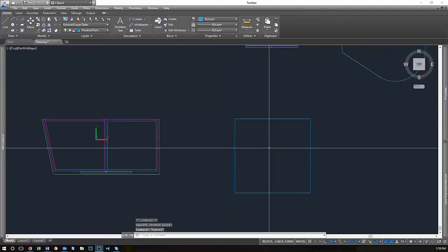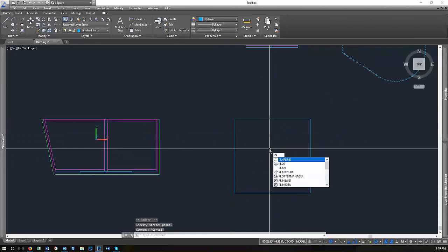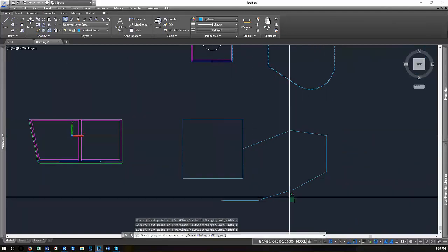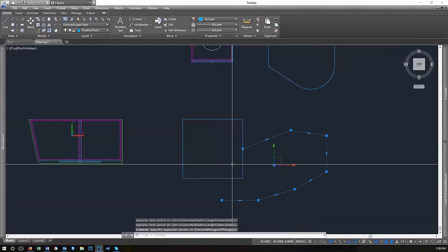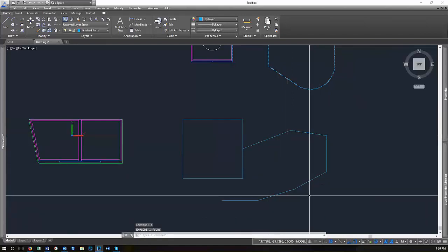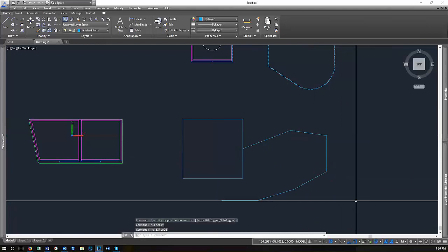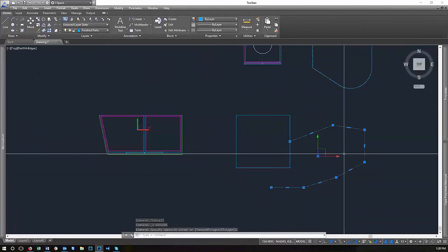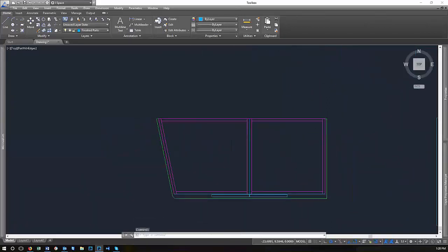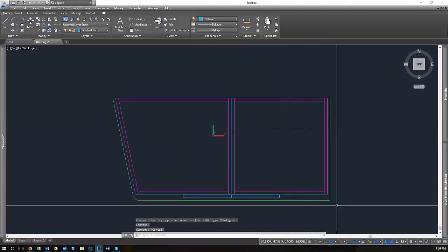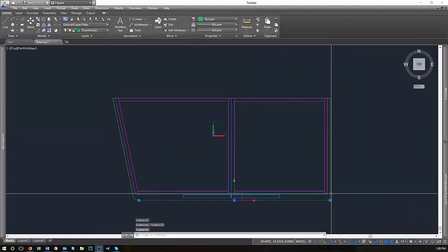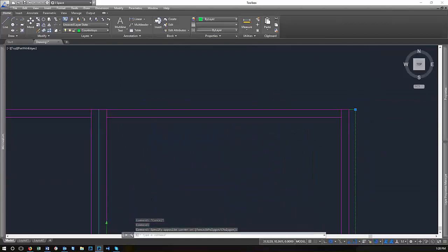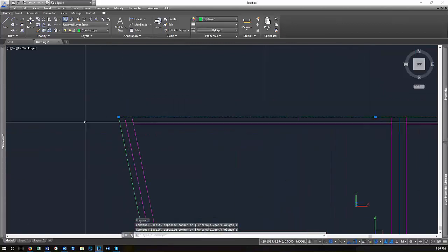And you can create one freehand by hitting PL. So that's a polyline. And you can click, and then wherever you click around the screen, it's going to make one contiguous line. And then once again, you can use the explode command to turn those into separate lines. But if you wanted one continuous line that you could select all at the same time, then you could have a polyline. Typically, I'll have my countertops be a polyline, and that allows me to select the entire countertop all at one time instead of having to zoom in and grab different pieces of the countertop at all the times.